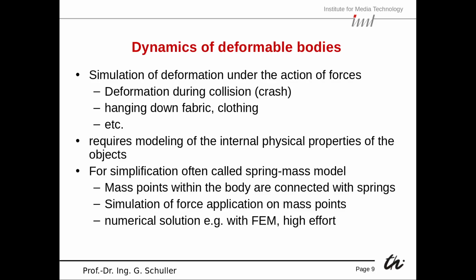So the mass points within the body are connected with springs, and then we have a simulation of forces and their application on those mass points. And we can use the numerical simulation using finite element models, which often means we have high computational complexity.